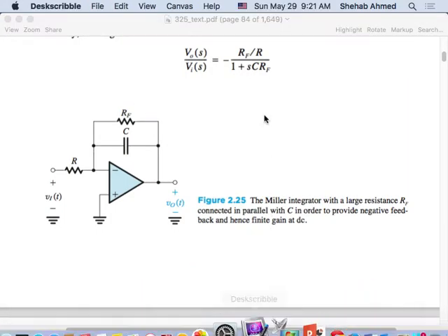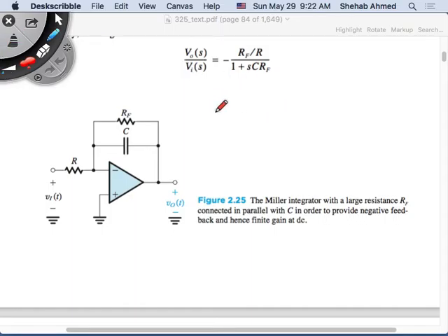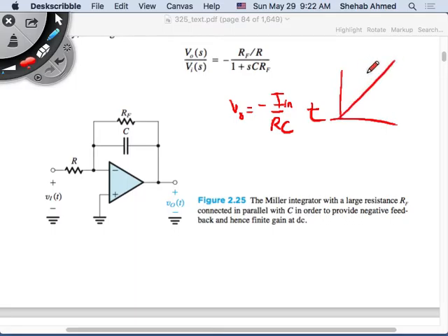So in the case of the capacitor only, we derived the output voltage equal to minus RC times the integration of I, and assuming I is a DC value, let's say I input, it's the integration of 1, which is T, from 0 to some time T, right? So this looks like what? Sorry, a ramp, but a negative ramp. Do we agree? We're okay with this? So it's a negative ramp.